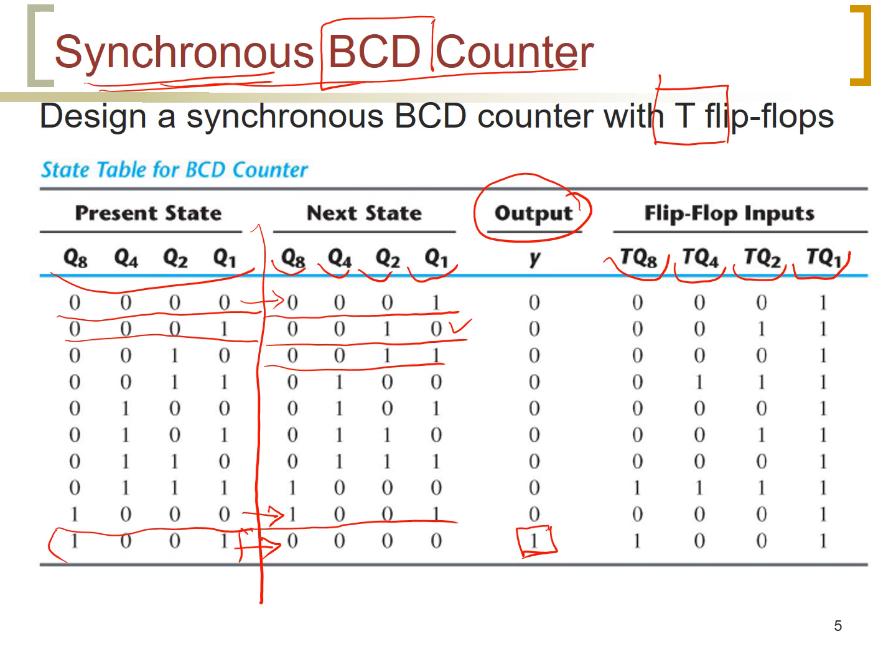And we simply find that TQ1 will always be 1, because if it is 0, it goes to 1, and if it is 1, it goes to 0. Similarly, we derive the value of TQ2, which is, again, the first time it will go from 0 to 0, so TQ2 is 0. Next time, 0 to 1, so TQ2 is 1, and so forth. We derive it this way.